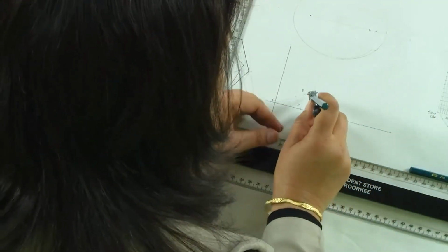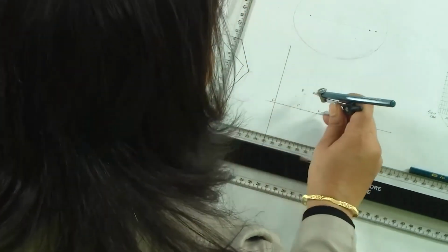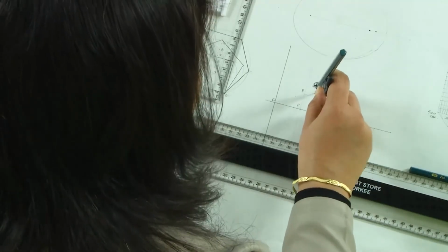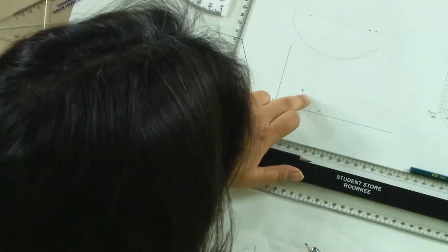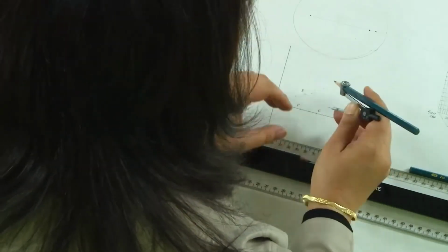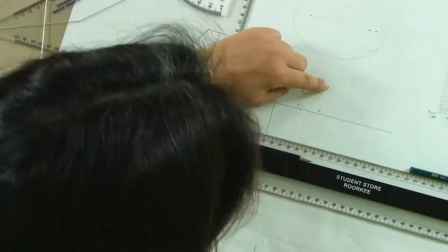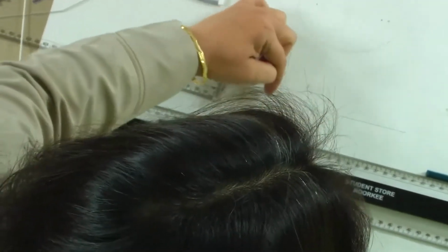Now next we take this point and we cut the same distance from the point F on this given perpendicular line. This is the point here, and then we measure this distance to a point on this line, which is the tangent CE, and then cut the same distance on the perpendicular line, taking the distance from the focal point F.